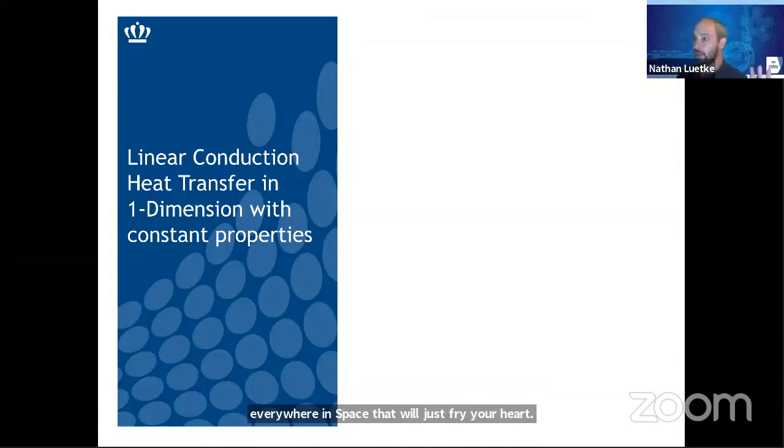Now, we could insulate a space vehicle with water bladders. Hydrogen is a great way to mitigate that, but the problem is it's very heavy. So we have to find ways to intelligently arrange the radiation shielding based on the application. If you're just flying to Mars, okay, where's the sun going to be coming at you? You've got to do it right. If you're going to build a Mars base or a moon base, where do you want to put the radiation shielding to protect the equipment and the astronauts?